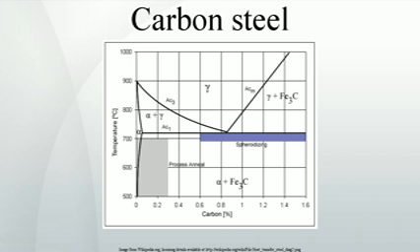Austempering. The austempering process is the same as martempering, except the steel is held in the molten salt bath through the bainite transformation temperatures, and then moderately cooled. The resulting bainite steel has a greater ductility, higher impact resistance, and less distortion. The disadvantage of austempering is it can only be used on a few steels, and it requires a special salt bath.